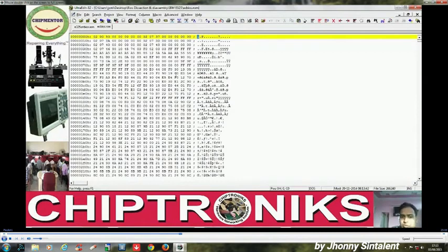I have gone up to 002 up to there. I have selected that data and deleted the rest. That is our system BIOS. We again reopened this file and we deleted the 2 MB. 2 MB is 2048 KB, which is equal to 2048 into 1024 bytes. We have deleted those bytes. The rest of the file is the EC file. This is very simple, so I have started with a simple procedure. In the next BIOS dissection, it will be a little tedious.